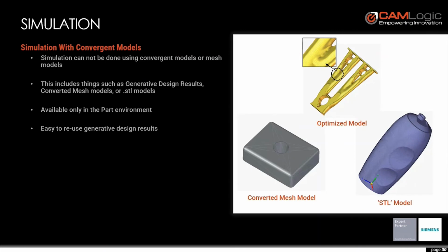So if you run a generative design study, the results it gives you are going to be partially a mesh. What remains of the original design will still be VREP data. However, afterwards, the result is probably going to be a hybrid model. An example would be this yellow model here. These flat faces are still VREP data, but all of these strut-shaped pieces are going to be mesh, and you can see that with the zoom up here.